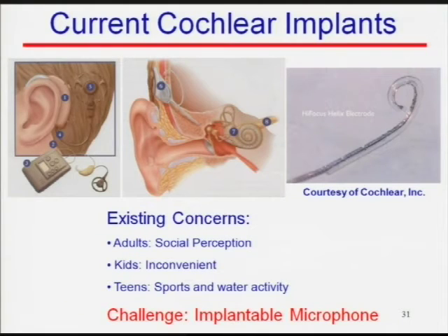So people developed cochlear implants. In this picture, it shows two coils. One is outside the head. The other one is implanted underneath the skin, with a separation distance on the order of about 5 to 8 millimeters. And this number 5 is basically a magnet, to make sure that the thing does not fall apart. It's positioned in alignment with the implantable subcutaneous coil.